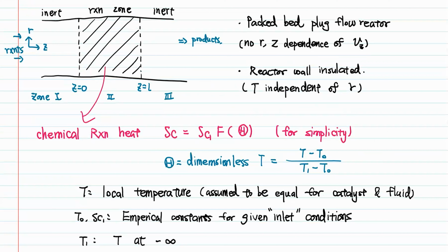My takeaway is that you typically define the thinnest part of the shell parallel to the direction of energy transfer, or parallel to where temperature will be changing. In this case, as your reactant flows over the reaction zone, a chemical reaction occurs, so the temperature should be changing in the z direction.